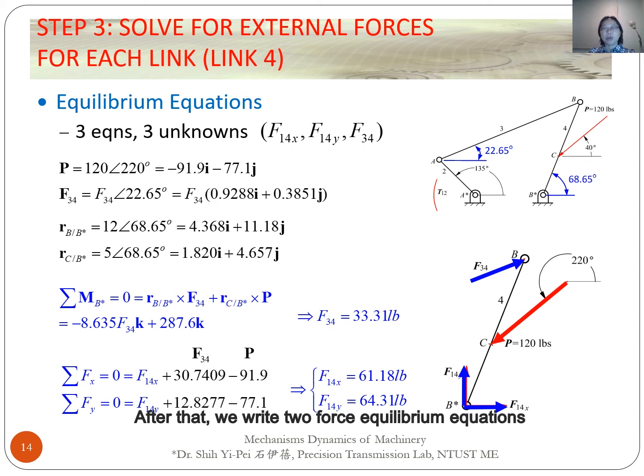After that, we write 2 force equilibrium equations, in which there are 2 unknowns, F14x and F14y. They can be figured out as 64.18 and 64.31 pound force, respectively.